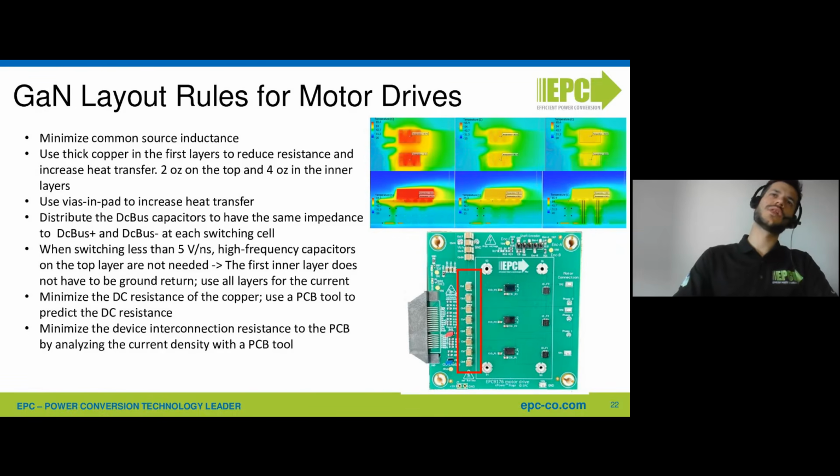The electrolytic capacitors take care of reducing the effect at switching frequency level, while usually the decoupling capacitors are meant for operating at the transition switching level. So we are talking about tens of megahertz instead of tens to hundreds of kilohertz.